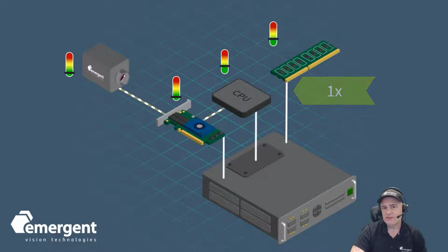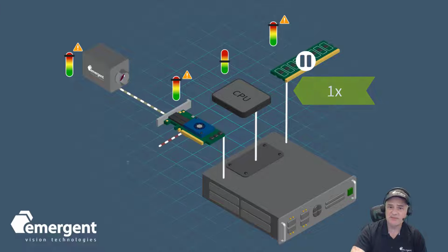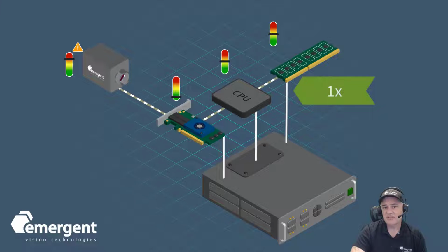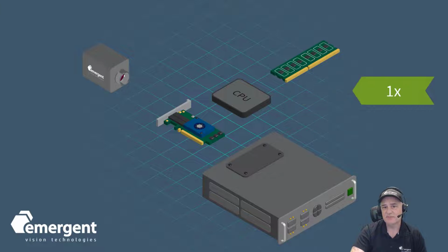This short animation illustrates the zero-copy memory bandwidth usage of an RDMA-based system. We see in the first part of the animation the system is not optimized, and thus even the appropriately sized buffer in the network card overflows. The difference compared to CXP is that for RDMA, the camera maintains a buffer and a resend mechanism to deal with system backups. The problem is that this buffer can also overflow, which again leads to data loss. In the second part of the animation, data flows freely and reliably thanks to zero copy and system optimization.